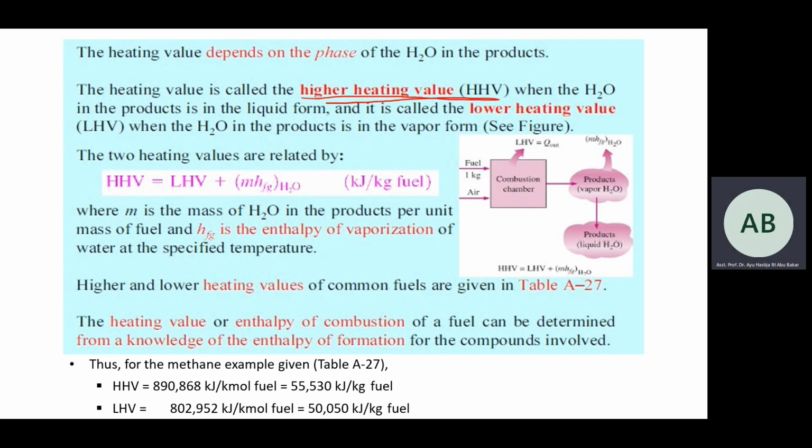Okay, remember in chapter 1 for the calorific value calculation, NCV, GCV. It is also different when you have water in liquid and water in vapor, right? GCV is HHV when the water is in liquid form.